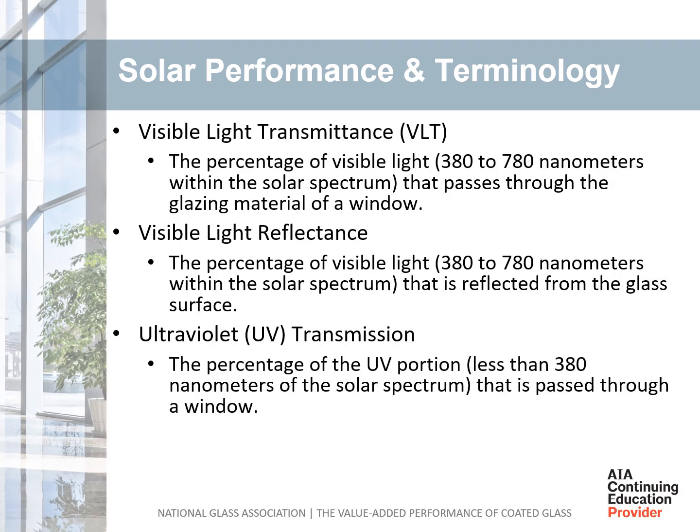A certain amount of solar energy is transmitted through the fenestration product in the interior of the building. The coating design engineer has the ability to impart changes to the glass properties, such as visible light transmission, or VLT, which affects daylighting amount and glare, or UV transmission, which can cause damage to surfaces, flooring, and fabrics.